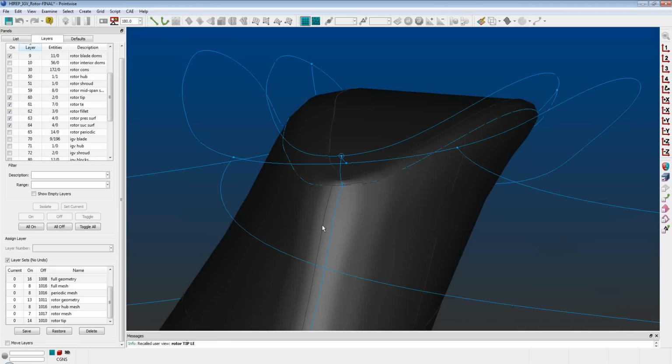So you can see the seam and the geometry running down the leading edge is a little bit offset from the true leading edge of the blade. So I actually moved the connector slightly to the right, closer to the true leading edge, and I did this because it worked better for my topology and actually increased the quality of my mesh at the leading edge.